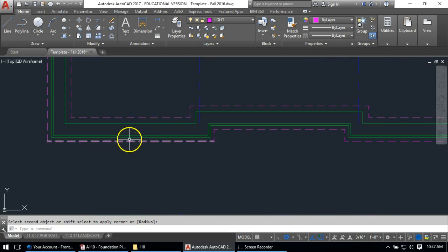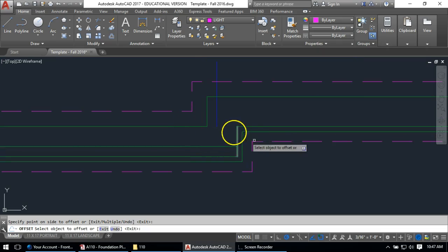And down along the bottom wall, we also have a brick line, and I sort of pre-included this. If we look at the details of this, it says we're going to have a 4-inch brick here. I drew it 12 inches because the whole thing is 12. That makes an 8-inch foundation wall. That's the result. But I need this 4 inches, so I'm going to offset 4, and I'm going to come up that way and come in here and here.